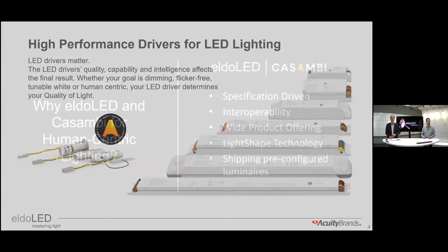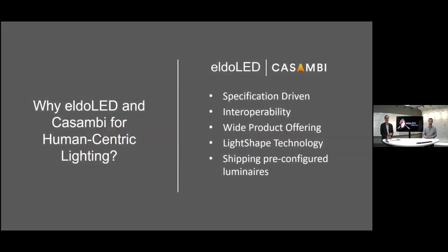Exactly. So first of all, let's start with why that combination, right? Why that combination is so crucial to do eldoLED and Casambi in this space. There are not that many two-channel drivers out there in the market. And to do tunable light, you need at least a two-channel driver. At least two channels. At least two channels, indeed. So given the fact that there are not that many two-channel drivers out there in the market, eldoLED is, especially in the human-centric lighting approach, a preferred brand for LED drivers.